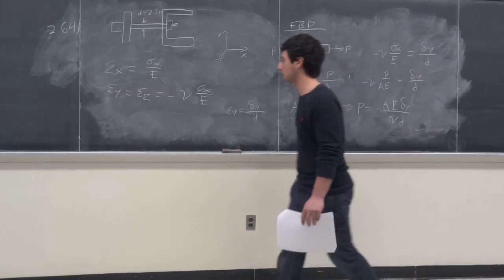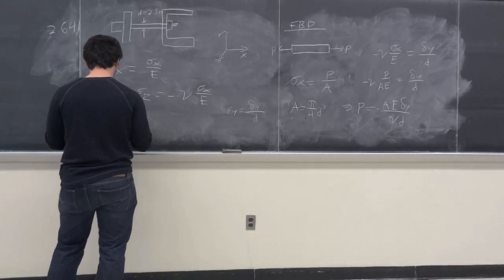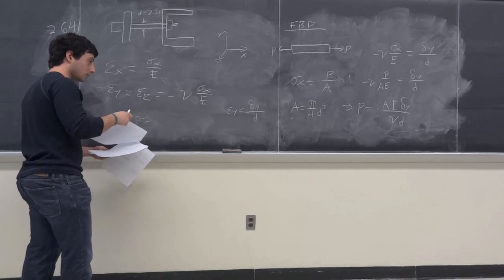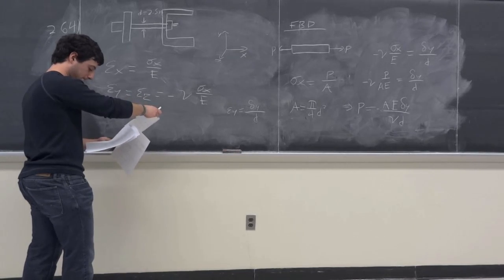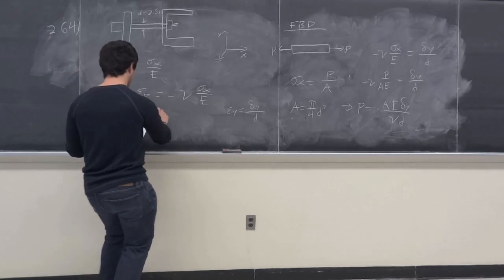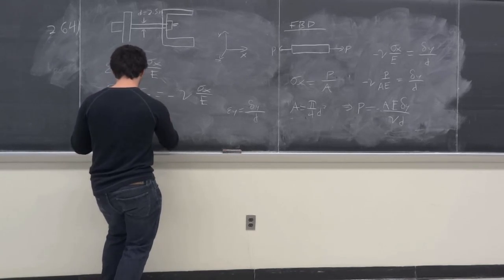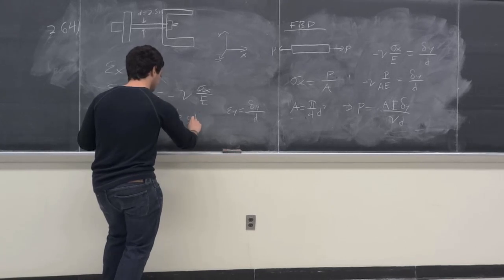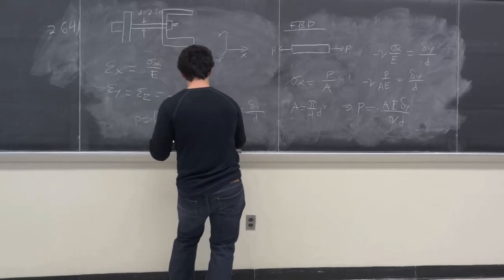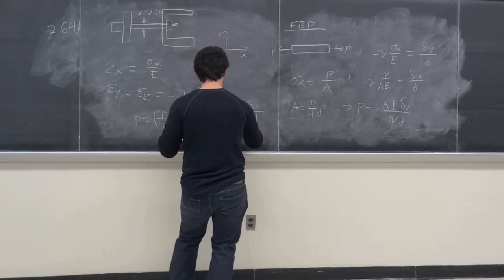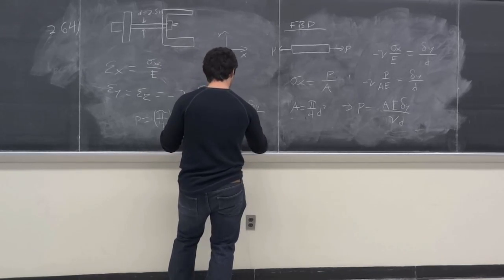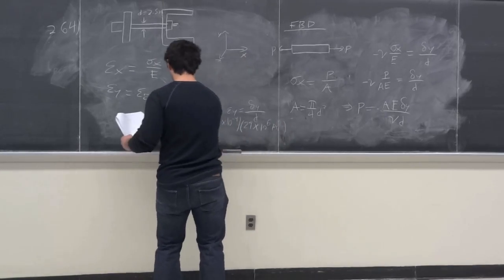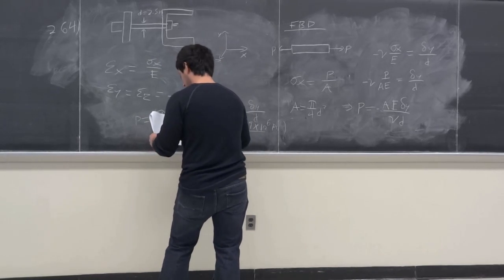All right, so for the force, after you plug in the values, P is equal to, I'll just write it out, minus pi over 4 times 2.5 inches squared times minus 2 times 10 to the negative 4, multiplied by 29 times 10 to the 6 psi, over 0.3.